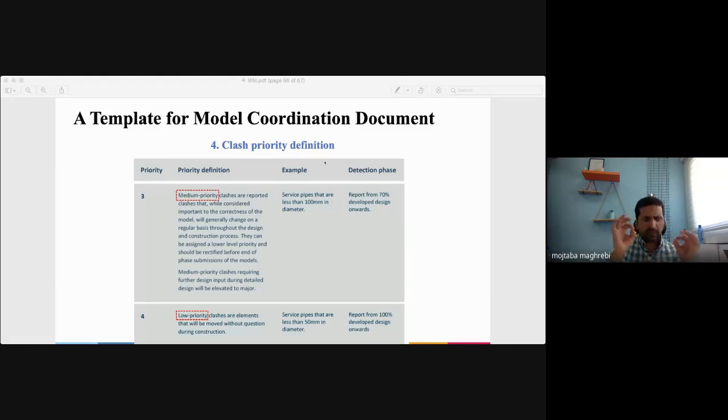One of the simplest advantages of BIM is clash detection. You can overlay all of those objects in one model, a federated model. And by one click, it says, okay, you have a clash between this pipe and these walls. And before you start the project, you can resolve these problems, rather than waiting until you construct the shear walls and don't have any room to pass these ducts.